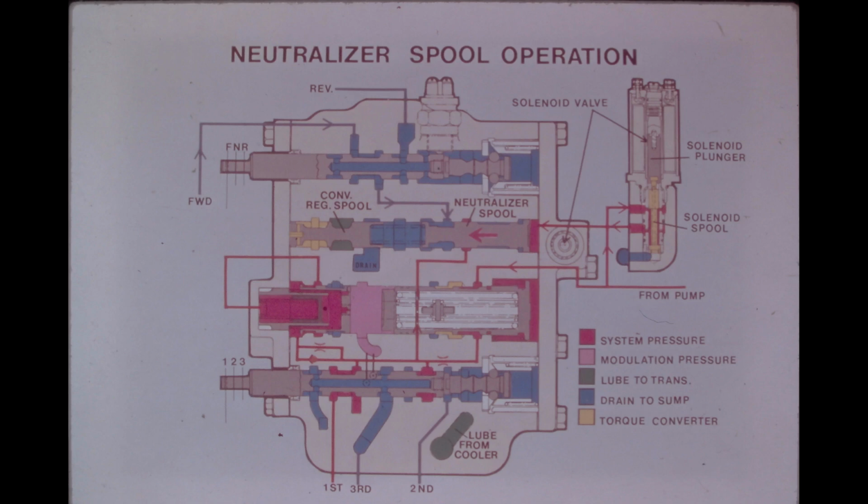Under these conditions, pressure would not be cut off to the directional spool, and the transmission would not disconnect when the left brake pedal was depressed. With the ignition on, an audible clicking should be heard when the left brake pedal is depressed. If not, a volt-ohm meter can be used to isolate the location of the electrical problem.